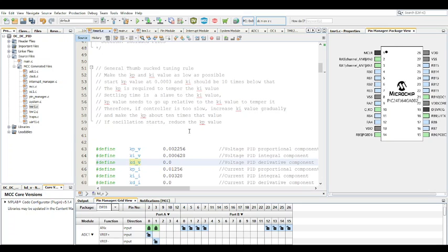Obviously on a professional scale, you have to get more specific with the control scheme, like a pole-zero compensator. But this is for a basic prototype. So a PI controller is usually good enough for that. So you start your values low. So I start them here. You notice when I run the SPICE analysis in Proteus now, it's quite slow. So you might have to change it for your specific application, but I prefer it to be slow at first. As long as we get to the set point, then I know I can make it faster.